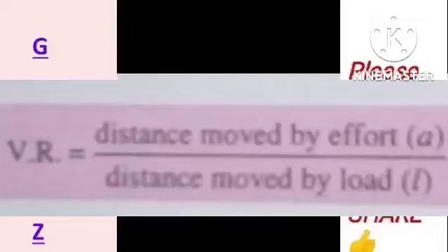Another terminology which we will deal with here is the velocity ratio, which is the ratio of the distance moved by the effort and load in the same time interval. Basically, it's the distance moved by effort divided by the distance moved by load. This velocity ratio is rightly defined because it represents the ratio between the velocity of the effort and the velocity of the load. So the greater the velocity ratio, the more useful work will be done.